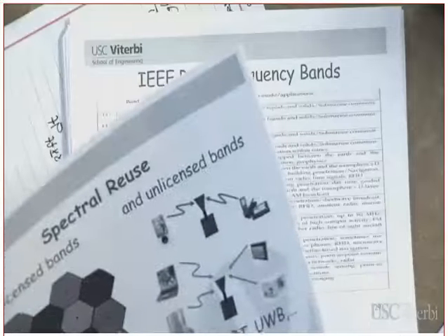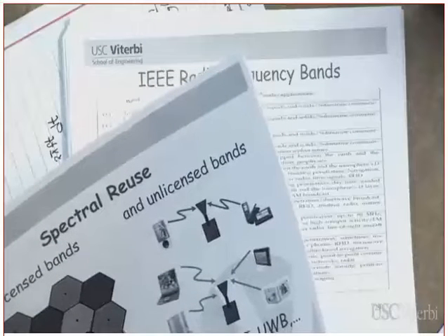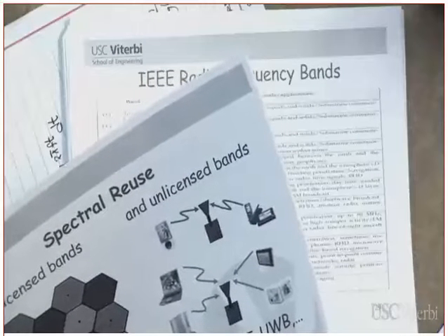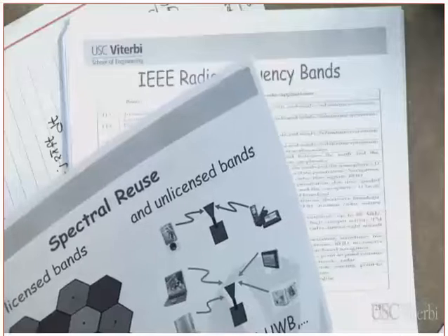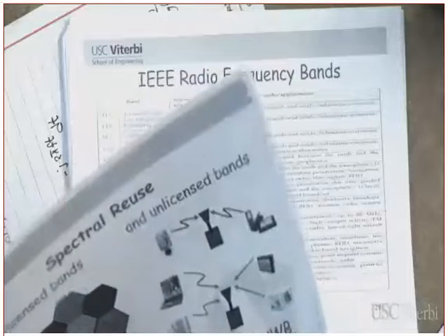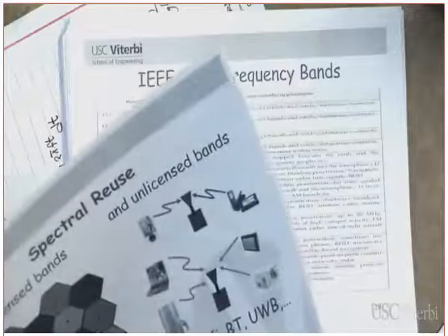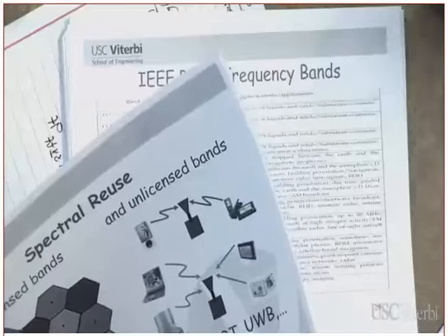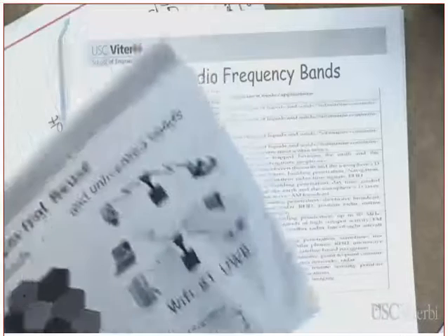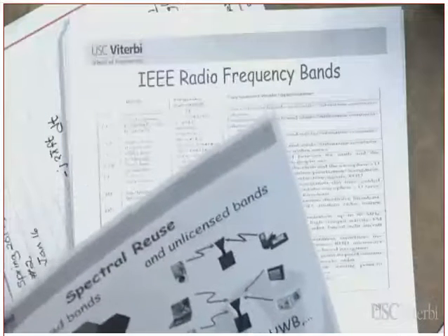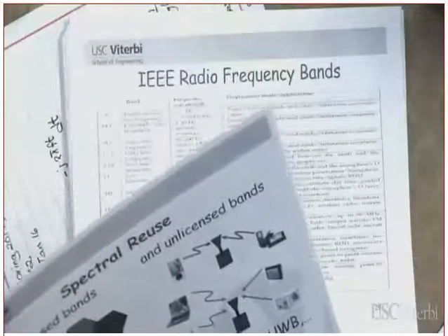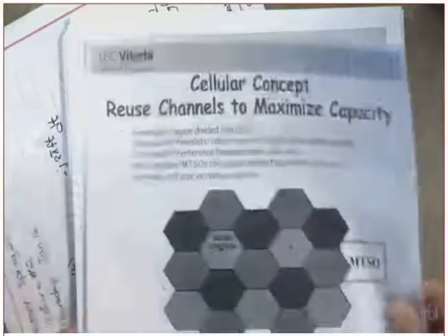Always remember the rule of thumb. When you design an RF system, at the beginning, you design it for coverage, which means you want to cover as much as possible. After you design it for coverage, then you try to improve it to increase capacity. The coverage becomes more important at the beginning than the capacity.